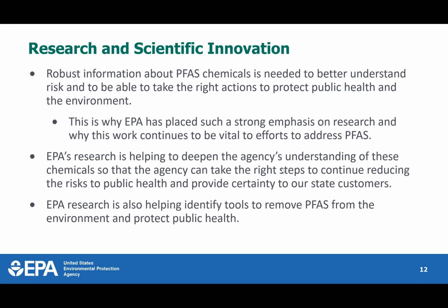Thanks for the question. The Safe Drinking Water Act, I think it's section 1414E, allows states to set more stringent standards than EPA, and essentially to have primary enforcement authority, for which a state must only demonstrate that its requirements are at least as stringent as the federal drinking water standards that are promulgated by EPA.